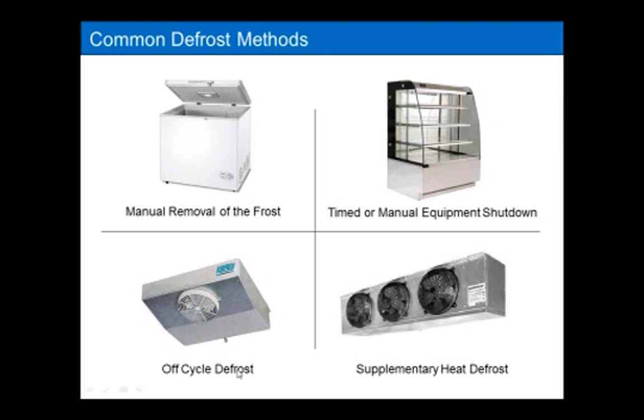But we will talk about this method down here, the off-cycle defrost method. Real popular method on defrosting medium temperature refrigerators, the typical system that you would see in a restaurant or a bar or food service. Your typical medium temp cooler is more than likely going to use some type of off-cycle defrost.